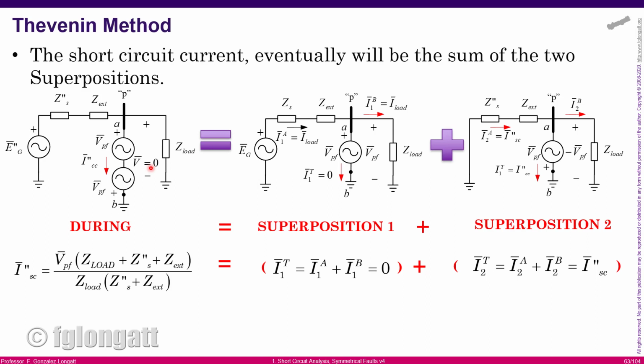The Thevenin voltage is coming from the voltage at the fault point previous to the fault. And the Thevenin impedance, well, in a basic circuit, you can use basic circuit analysis, series and parallel, or even in a bigger power system, you can use delta and star transformations, or even if you have a beautiful, very large power system, you can use matrices, impedance matrix and admittance matrix.